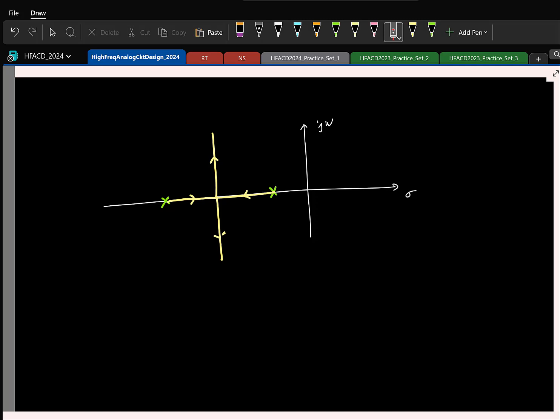Critically damped. Fast rising. Why is it fast rising? It's all correct. I am trying to ask you why more, so that you'll understand it better. One is decaying fast and one is decaying slow. Correct. But I guess at the intermediate point, that's the logic, right? See, as he's pointing out, if you have 2 poles, let us say the closed loop system has 2 poles, P1 hat and P2 hat, all my responses will have something of the form K1 e power minus P1 hat t.